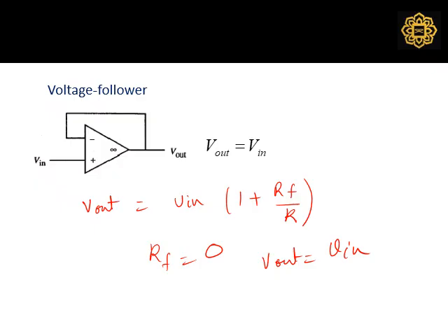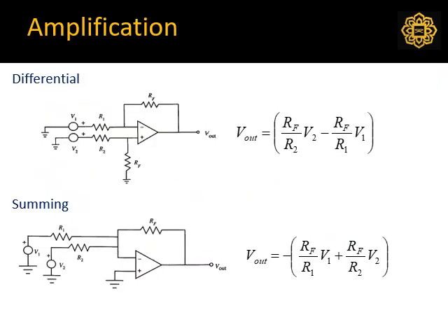You want to minimize the current drawn by the voltmeter, and still measure the voltage across the circuit. So you would like a device with the least loading effect, which does not draw current by itself and just measures the voltage in parallel. This is an example. In these cases, you may want to use a voltage follower type of circuit, which has high input impedance.